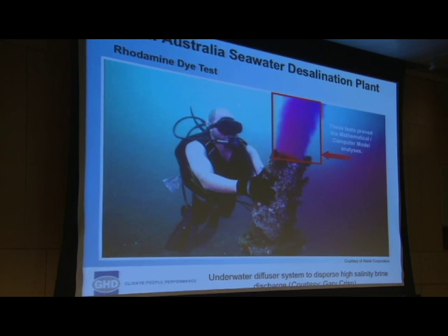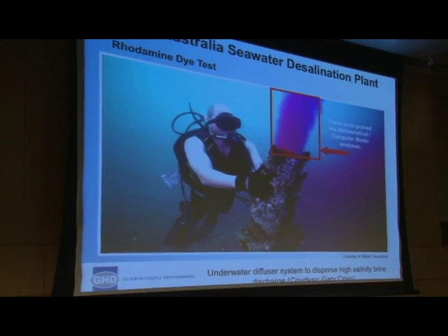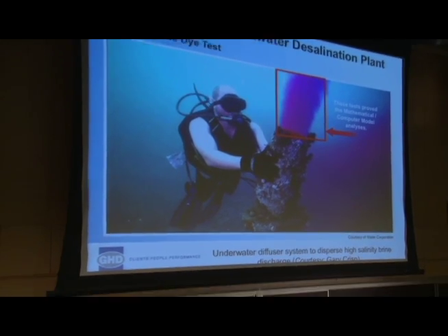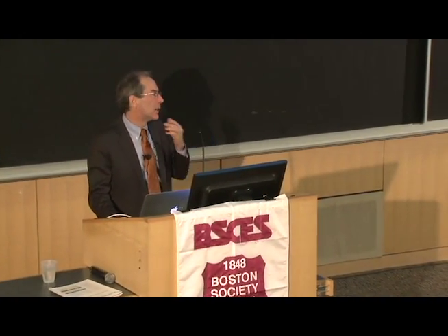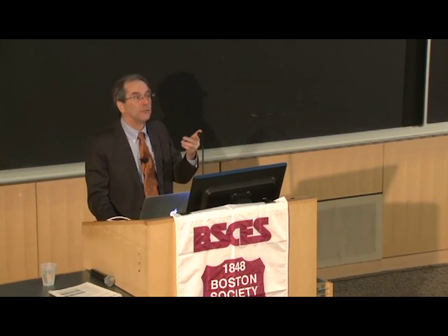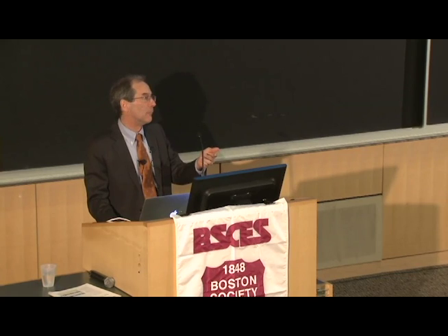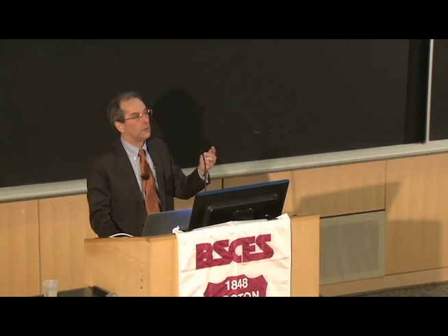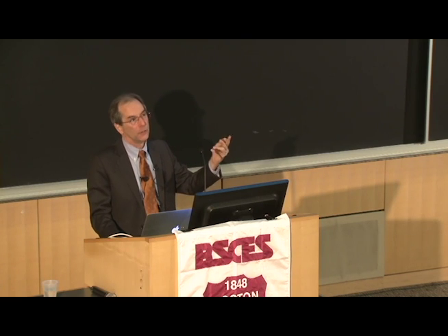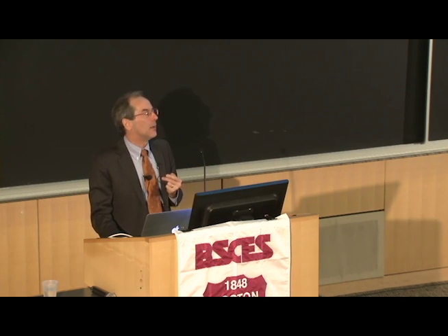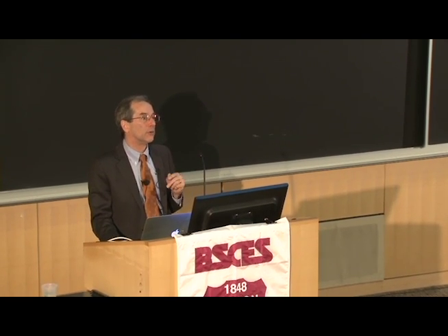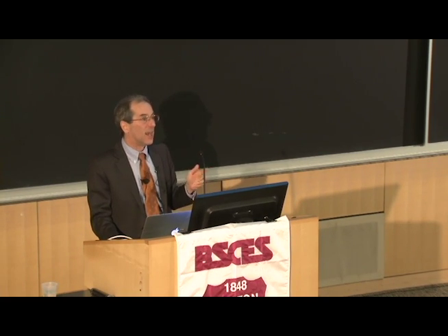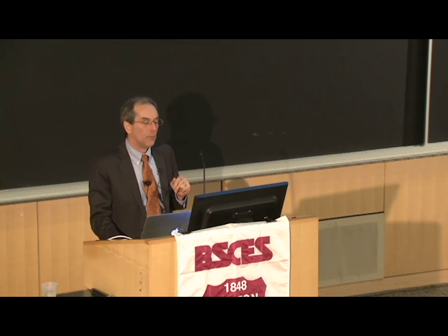Gary likes to point out that you've got marine life on the diffuser, but I think that may be oversimplifying a little bit. What's in this water that comes out? Well, salts. The salts that you had in seawater. Depending on the plant, there could be some residual chlorine, which would have a half-life of about 15 minutes in the ocean. Depending on the plant, if there are corrosion byproducts, they could include things like chromium. And so there are some issues to be considered when you think about what you're putting back in the ocean. What are the right concentrations and what's safe? At this point, what I have heard has been a lot of tug-of-war between people on both sides. I think it's an area where more research would go a long way to helping find good designs and good solutions for these plants. And that's ongoing.